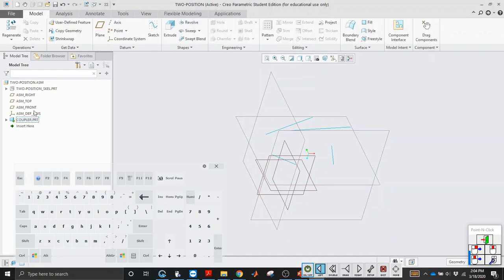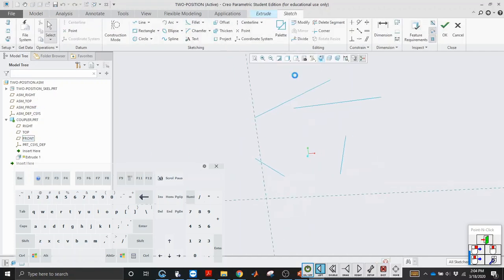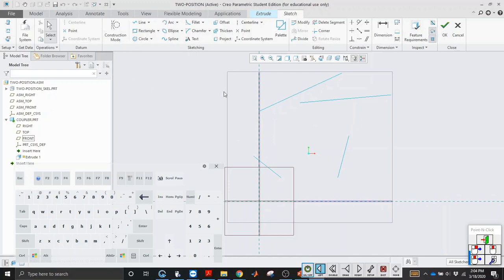And then we want to activate this, because now we're going to use the background references that we've developed in these sketches to draw our coupler. So the first thing to do is just going to be extrude out of the plane. So we'll go into our sketch, and now we know we need to draw a coupler that links these things together. I like some round things, so let's make these all the same diameter. Let's do 3/8 of an inch because it's a nice number. You'll notice I am very OCD when it comes to this stuff.